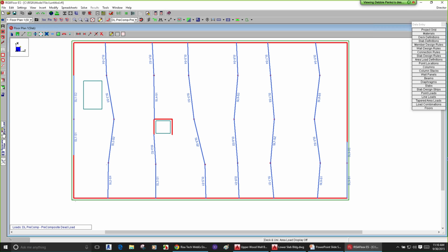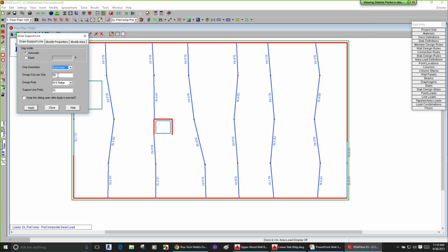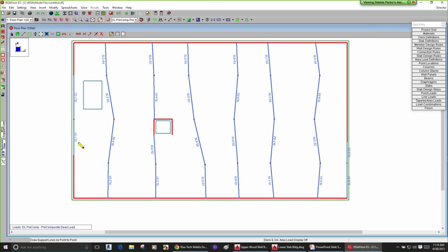I'm going to go ahead and do the other direction real quick. So we'll go east-west, in both ways, and we'll finish this up here. So clicking on that east-west direction. Of course, this is a two-way slab, so we're trying to click it in two ways. That's kind of the big point, right? You have to go in both directions in order to get designed properly, and the program will then create those design strips for you.